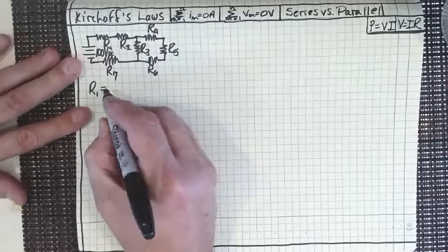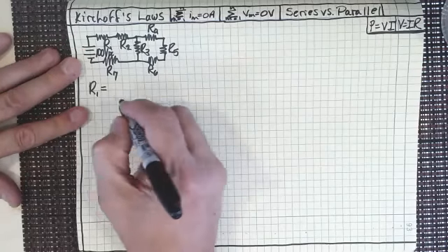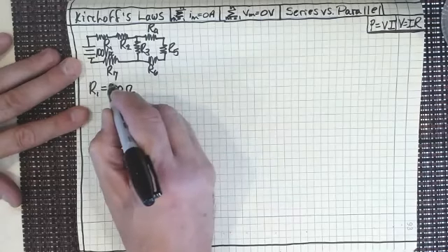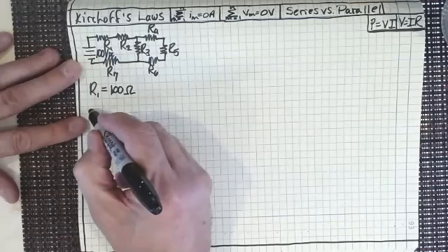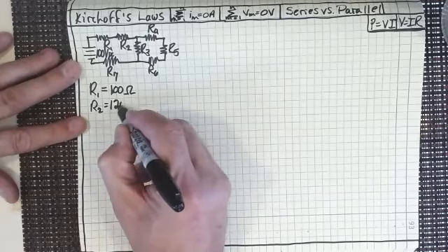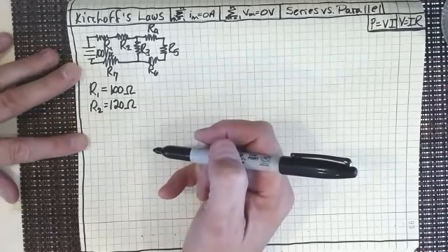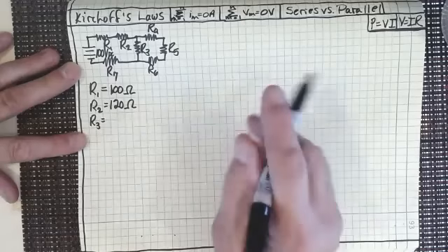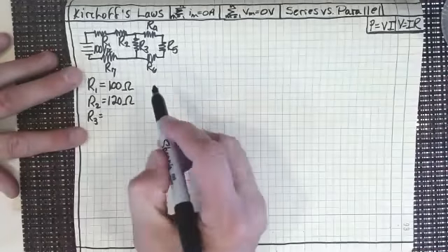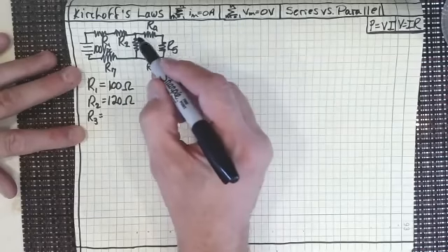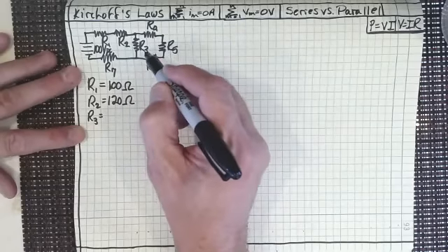All right, now let's go into this. So let's say R1 is just 100 ohms, right? We know that that's just a standard thing. And R2, I'm going to say, is 120 ohms. R3, we might want to keep that as sort of a standoff resistor so that not a lot of current flows through here and more current is going to flow through here.